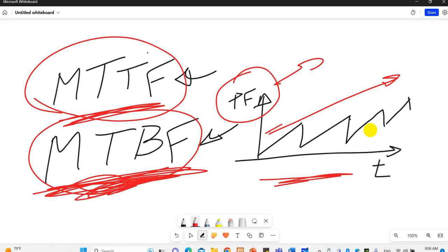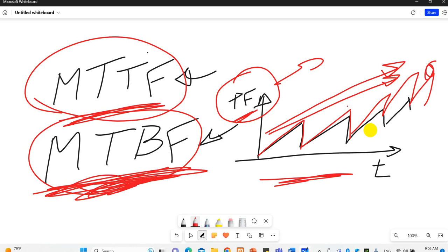But finally, you find that the probability of failure is increasing. Even after each maintenance, the probability increases and then goes down when you do maintenance, then increases once again and goes down when you do maintenance. Up again, and so on. But finally, we find that after a while the probability is very, very high. Why? Because it's lifetime. At this point, we take the decision to replace all these parts.